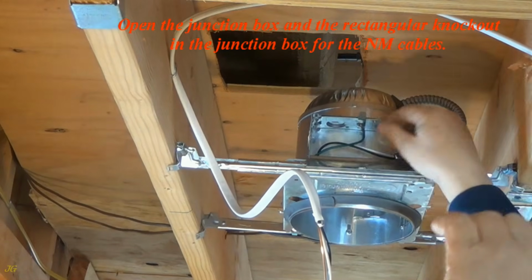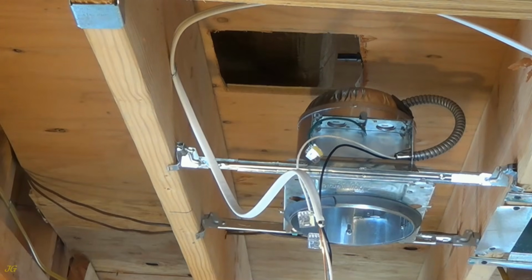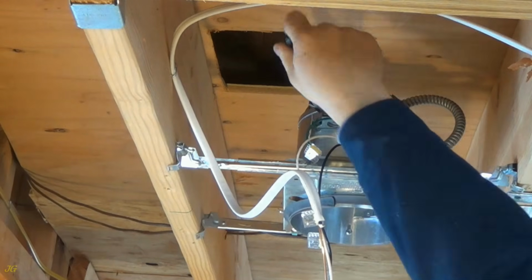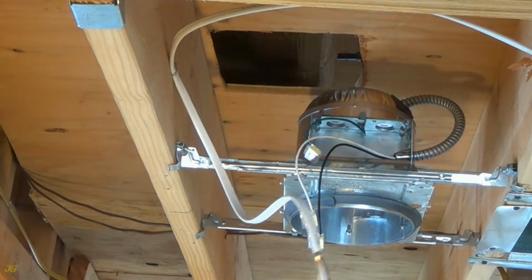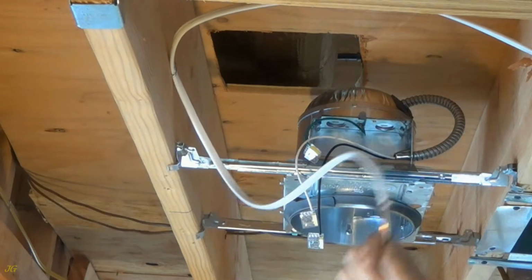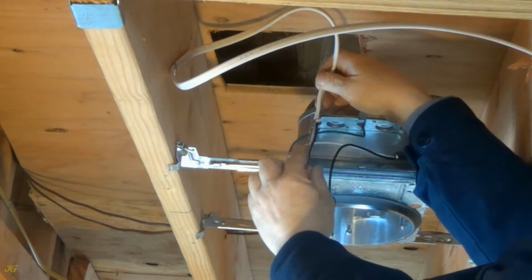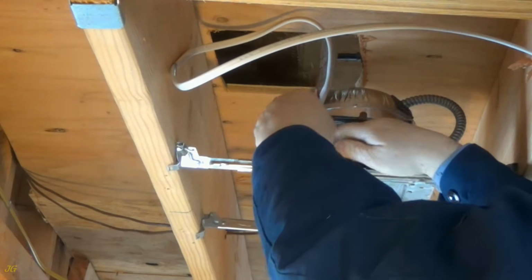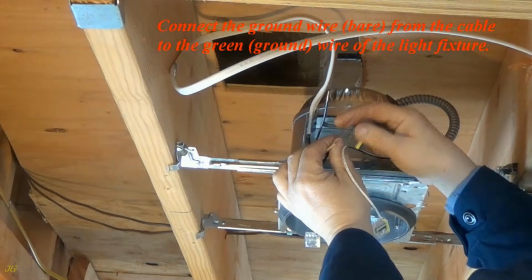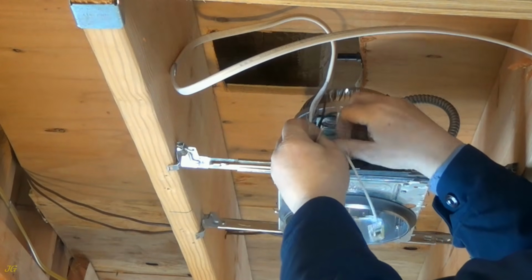Open the junction box and junction box rectangular knockout for NM cables. Insert the cable into the open knockout. Connect the ground wire, bare, from the cable to the green, ground wire of the light fixture.